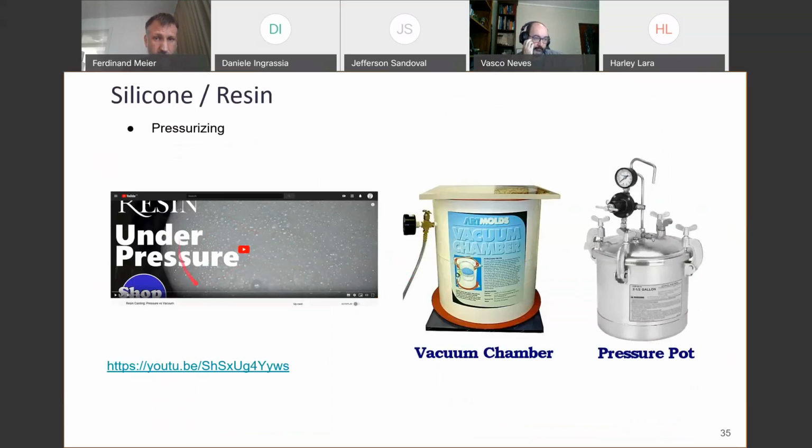This is a very nice video that shows you the silicone is mostly good to vacuum, but then for the casting resin, many times it's a good idea to put high pressure. And so he compares high pressure to vacuum. If you put high pressure, your bubbles just get very small until they become invisible. So yeah, many times it's a good idea to have high pressure for casting the resin and low pressure for the silicone.